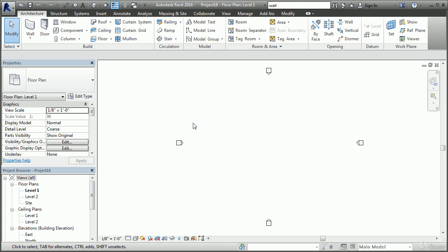To create an object in Revit, you choose the element category from the ribbon or the quick access toolbar, select the element type in the type selector, pick any appropriate options on the options bar, such as a location line or the unconnected height for your walls, and then you select points or host elements in the drawing area.